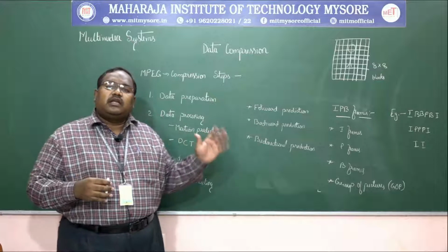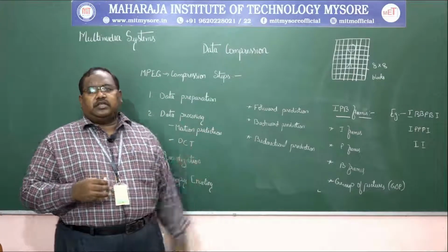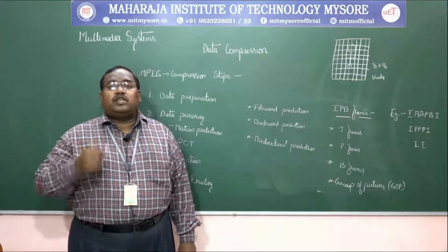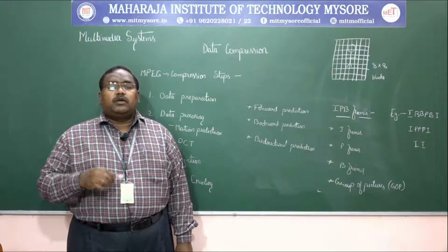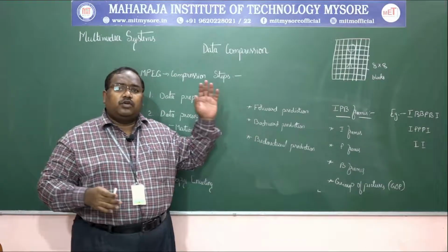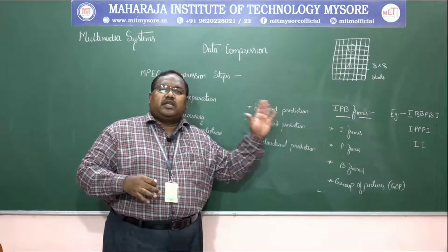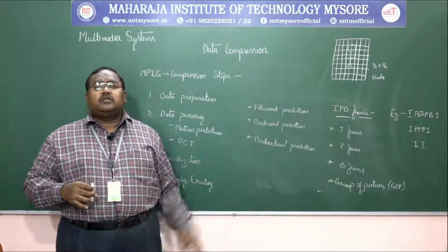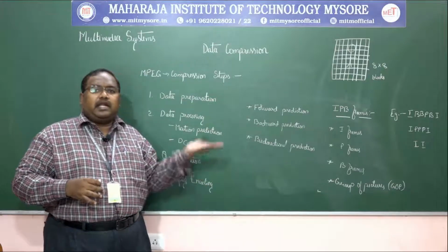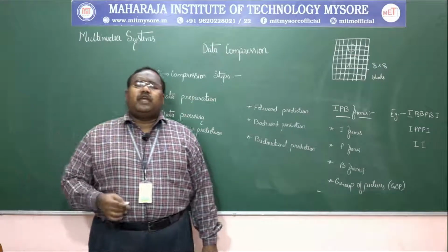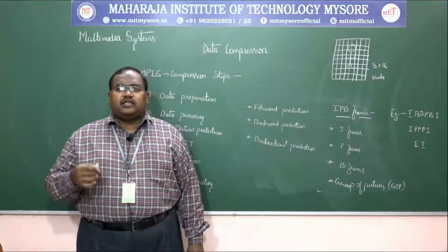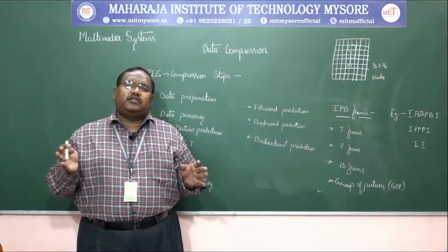So what we do here, we apply the quantization process on the frequency domain coefficients, because there are different coefficients. I have shown you how the 3-bit to 16-bit and 8-bit quantization has been done using the sine wave. So that same process is being applied here. To favor the lower frequency coefficients, we remove higher frequency coefficients.